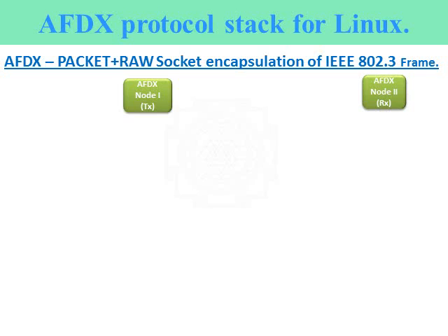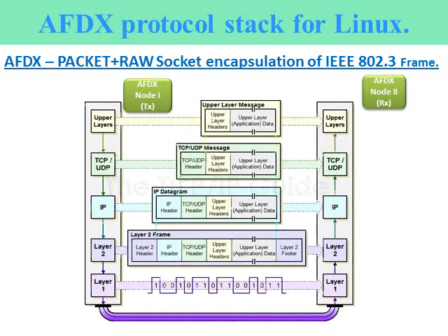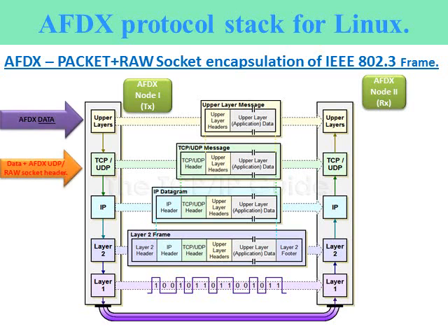So how I constructed my packet of AFDX frames, I am just explaining through this animation. Initially there is sensor data, then I am enveloping that with a UDP header, checksum, etc. Then using a raw socket, I am adding the AFDX message with UDP and passing it to the IP level. Then a 20 byte IP header with checksum, etc. has been added. Then it will be injected to layer 2 directly in the NIC card.